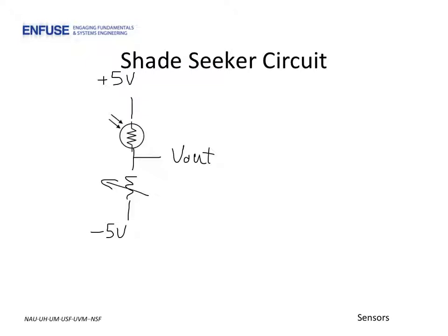The advantage of developing a microcontroller-based circuit is that you would not need to use a potentiometer necessarily, because you could adjust thresholds in your code. And likewise, you could have the circuit turn on or turn off the output depending on the threshold, and therefore use the same circuit for a sun-seeking or sun-avoiding system by simply altering the code that you write.